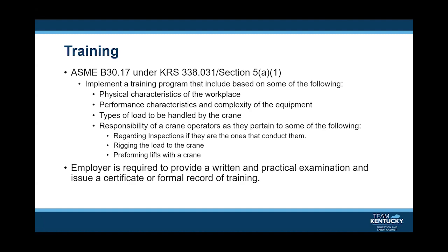When it comes to cranes that will fall under ASME B30.17, the requirements are more stringent and are very similar to the requirements of a powered industrial truck program.